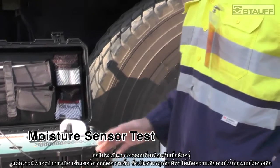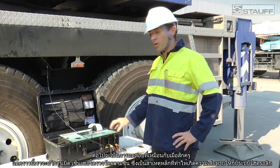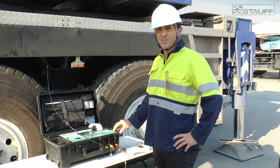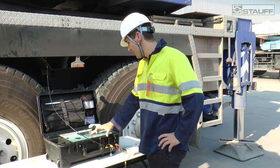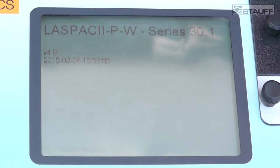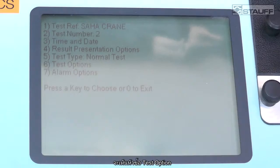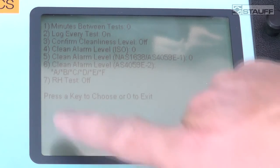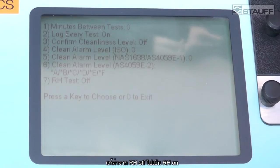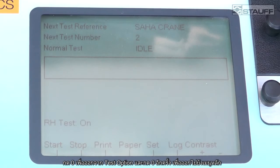So now we're going to do a similar test, but this time we are going to turn our moisture sensor on, as water is also very damaging to our hydraulic system. So we want to see the moisture content of the actual oil. So I just need to change settings slightly. We turn the particle counter on, we go into the settings, and in the test options menu, press 6. Change RH test off to on. So press 7, change to on. Press 0 to exit, 0 to exit again, and we're ready to take the test.